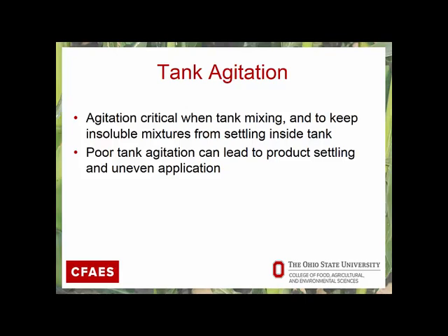I mentioned tank agitation. Agitation is critical when tank mixing, to keep insoluble mixtures from settling inside the tank. Especially the wettable powders, the water dispersible granules, the flowable products, these will tend to settle out, so agitation not only during mixing but throughout your application is critical.